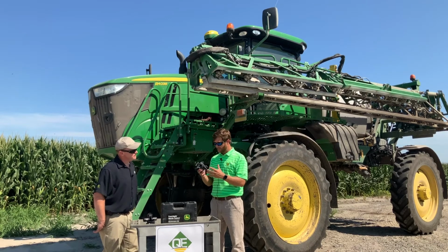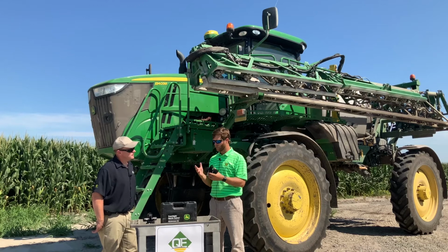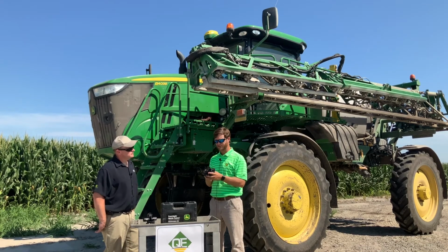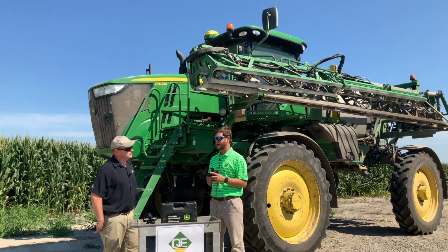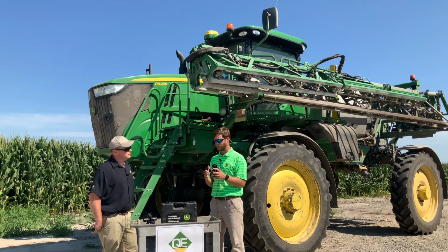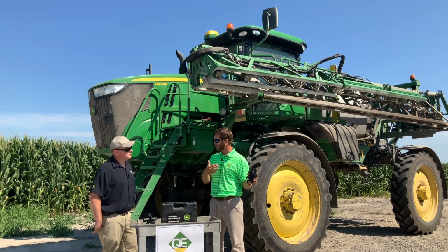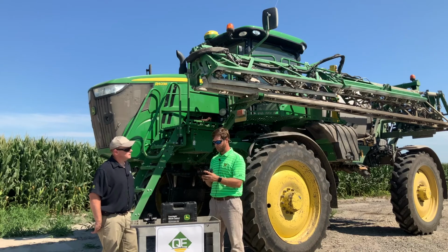Yeah, as technology is expensive, we continue to talk about our return on our investment. And one of the capabilities is turn compensation, where if you think about field irregularity and a lot of point or pinch rows, as we continue to swing the boom, our conventional systems would burn more on or over apply on the inside of the turn, and then under apply, not hitting our desired rate on the outside of the boom.